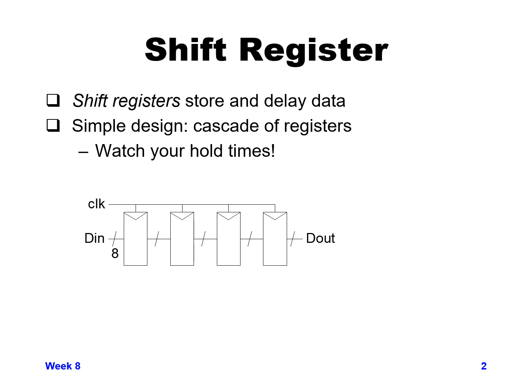comes in from a data value 8 wide bus, and it goes into a next set of 8 in an 8 wide bus, and so it takes 4 cycles for D in to get to D out, and in this particular case it just shifts through, and 4 cycles later D in comes out at D out, and in the meantime it's just storing 8 bits wide. It's storing 4 values in series before it goes from in to out.